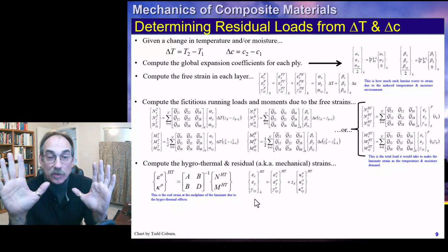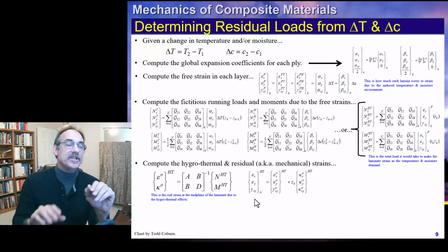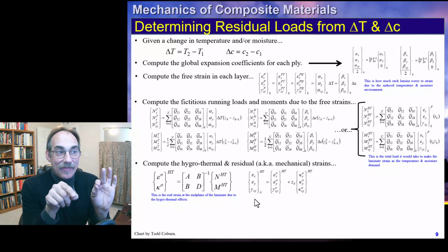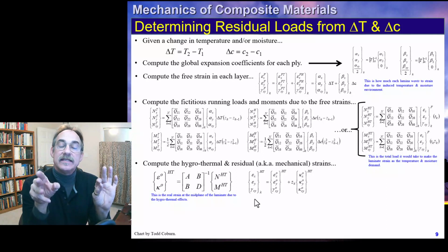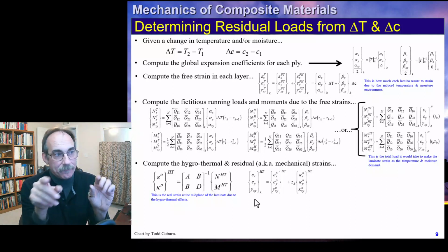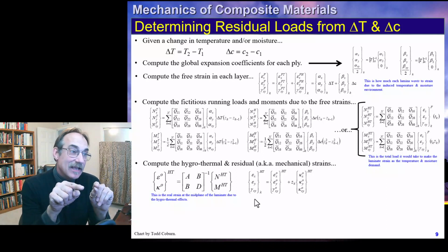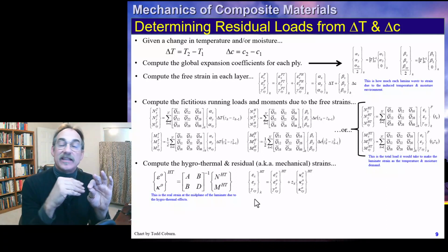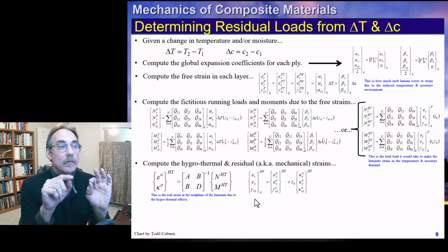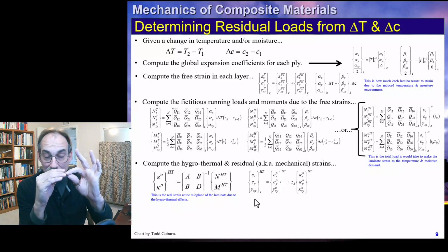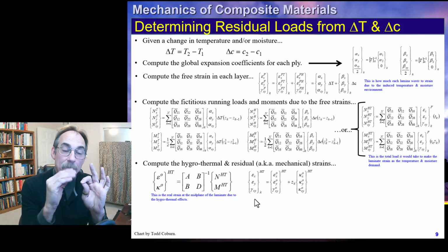If we have 5 plies, we're going to do 5 more calculations where we're going to take the midplane strains and add them to the Z-bar times the curvatures. Okay? Now, this shows Z in our slide, because we can use this to calculate the strain anywhere. But what we're going to insert here is the Z-bar of every ply, that midplane value, the Z-bar.